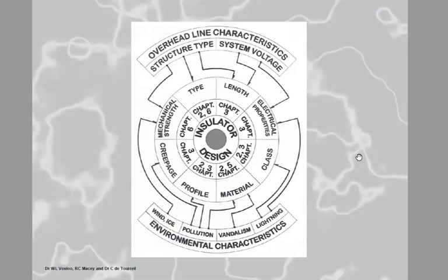Now, the high voltage insulator needs to support the conductor mechanically, and it needs to insulate the high voltage from earth potential. Now, if that insulator fails, the line is down, or the line is short-circuited to ground, and we have a flashover and the line is taken out of service, which means loss to our customers. So the high voltage insulator is actually the backbone of our network.